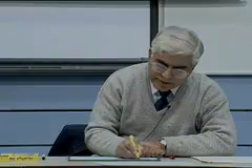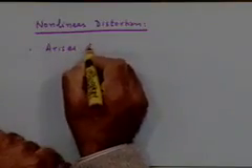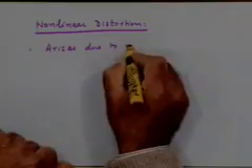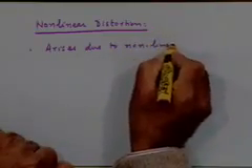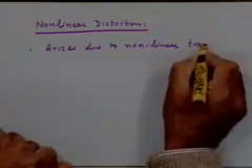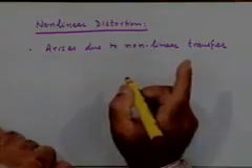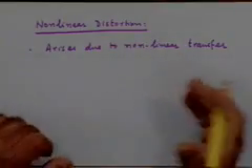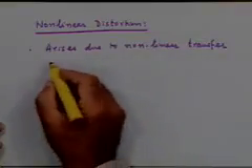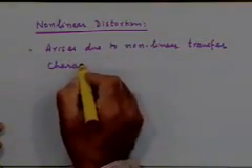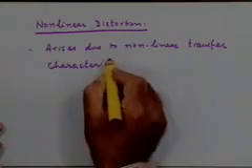So let me first mention what nonlinear distortion is. So this arises due to nonlinear, now please note what I am writing, nonlinear transfer characteristics, not transfer function, because nonlinear systems I cannot study in terms of transfer functions. I mean we are not talking about the frequency domain here. I am saying due to nonlinear transfer characteristics. What are the transfer characteristics of a device like an amplifier?